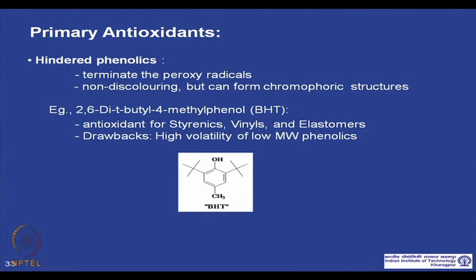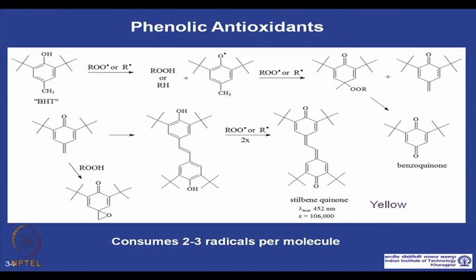But the drawback for these primary antioxidants is that they form very volatile, low molecular weight phenolics, so they might get lost during the processing conditions. So, this is the mechanism by which they work.